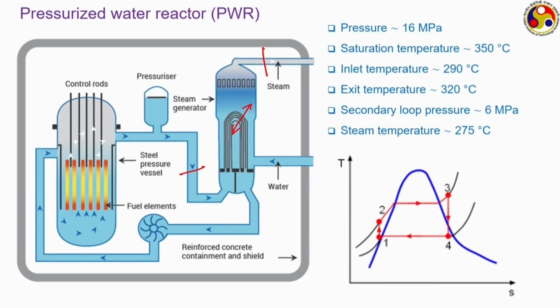This steam is then taken to a Rankine cycle, a conventional Rankine cycle which may also contain reheating or superheating and even regeneration, but that part is external, which is similar to any conventional coal based power stations. In a nuclear power plant, we only get an efficiency between 0.2 to 0.3, similar to conventional coal based power stations, for the process that is done inside the boiler.